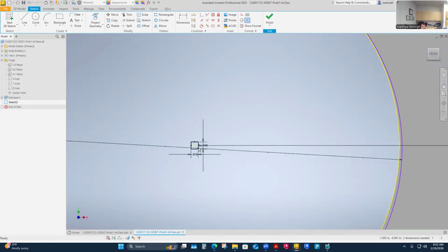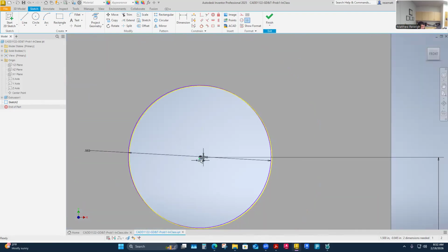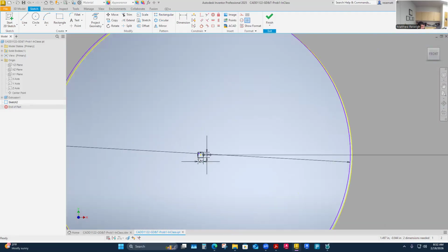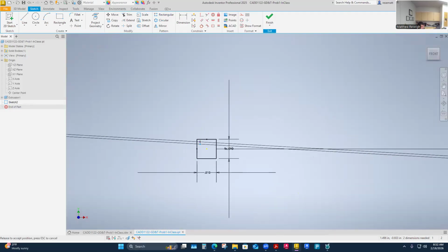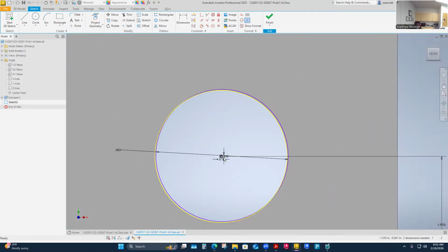So really you get this variation of where this hole can live when somebody's putting it in, in a manual drill press, if they're just going to manually drill it, or if it's going to be in a machine. The operator has all of this tolerance to work with. Well, it's not a lot actually. It's kind of limited, and it's an unusual shape to have a square tolerance zone around a round feature for sure.